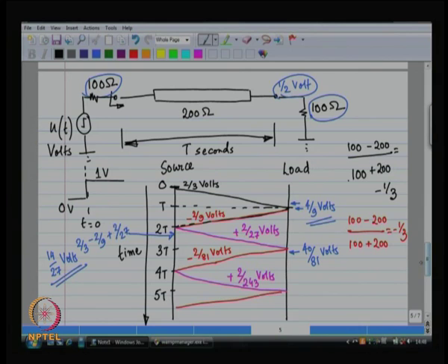In which case all of these reflections that we did in the time domain become much harder to do, because when the reflection coefficient is a complex number, you have to break up what you had transmitted, break up the waves in terms of sinusoids, and then when it is reflected you multiply it by the reflection coefficient, add the phase delay of the reflection coefficient, etcetera, and then you sum up all these waves and you end up with a big mess.